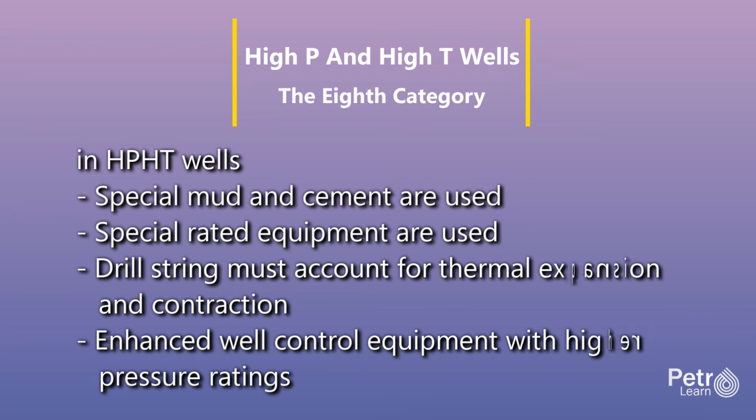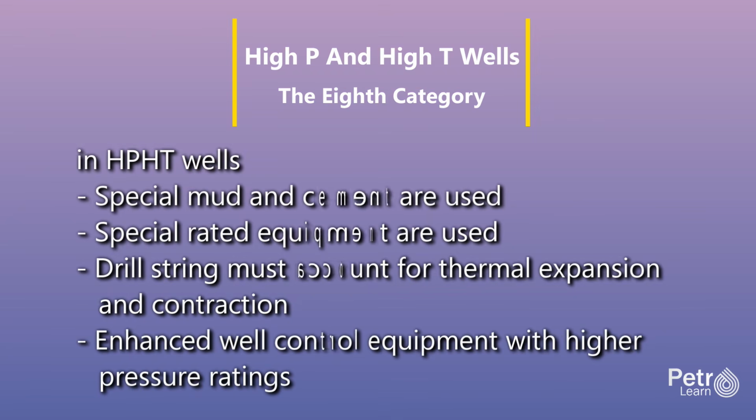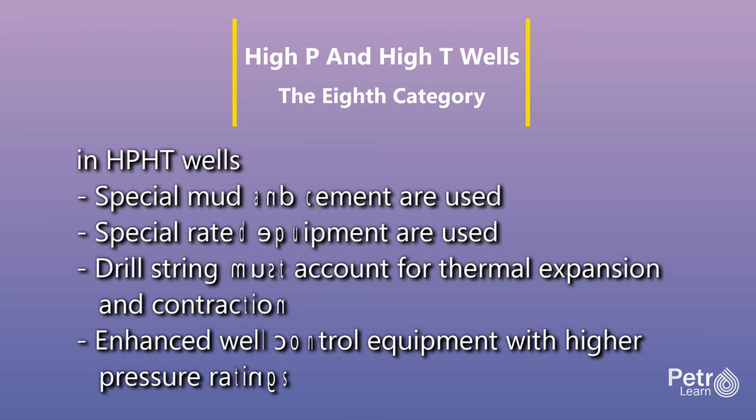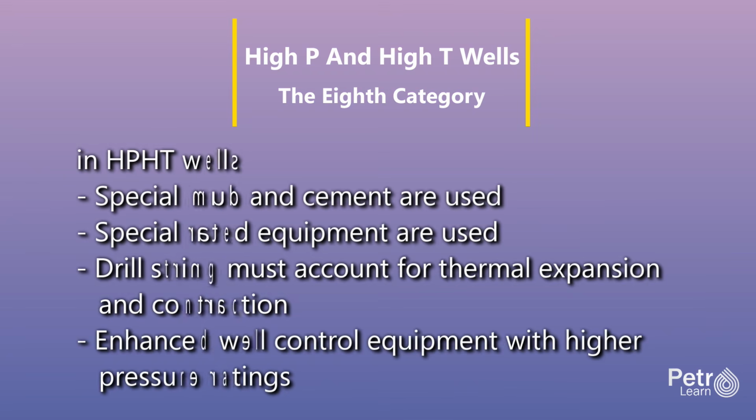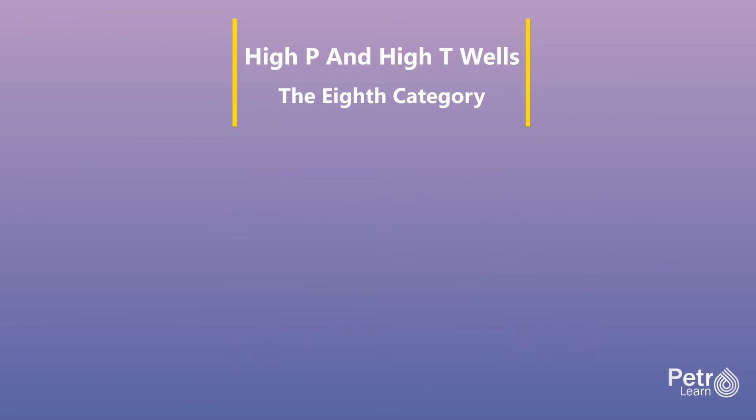Cementing becomes more complex as cement compositions must be engineered to set properly at high temperatures without degradation or strength retrogression. Drilling in HPHT environments requires enhanced well control equipment with higher pressure ratings, often 15,000 or 20,000 psi BOPs, more comprehensive monitoring systems, and highly trained personnel. Pressure while drilling sensors provide real-time formation pressure data, allowing early detection of overpressure zones before they cause kicks. Managed pressure drilling techniques, where surface back pressure is precisely controlled with automated chokes, allow drilling with narrower margins and better control than conventional methods.